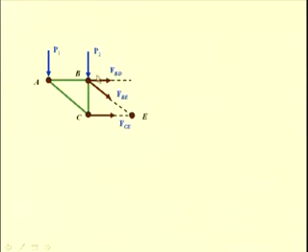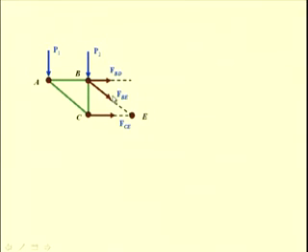In the same way, the members BD and BE are concurrent at B. So, the moments of the forces FBD and FBE are 0 about this point B, and if we take a moment summation about this point, it is possible to find the force FCE. And the third equation could be a force summation, either the summation of the vertical components or the summation of horizontal components can be equated to 0 in order to determine the force FBE.